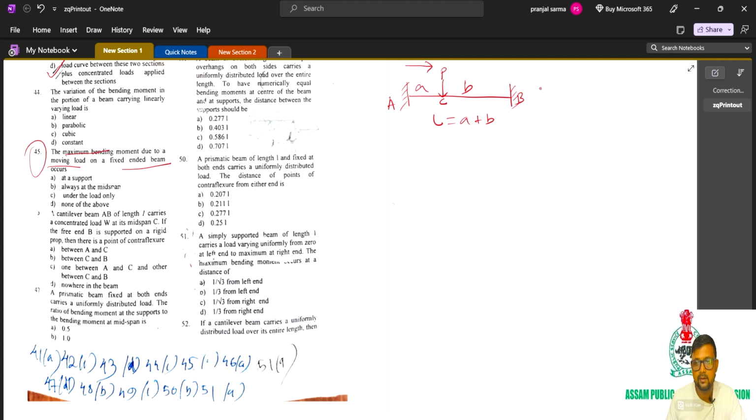First we find the fixed end bending moment diagram. Then we'll draw the free bending moment diagram. Then we'll superimpose and find the final bending moment diagram. Through that final bending moment diagram, we'll find the location of maximum bending moment.